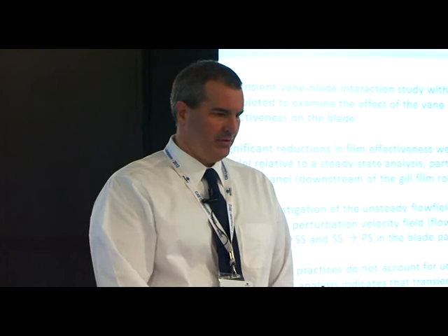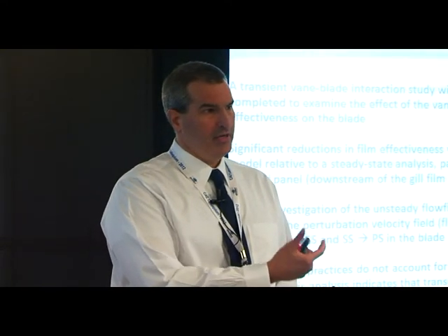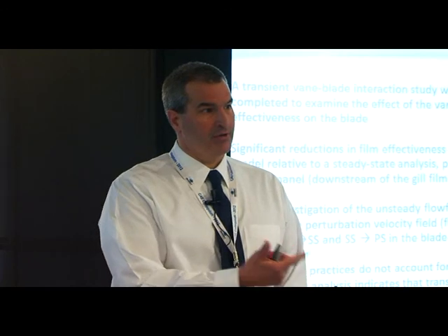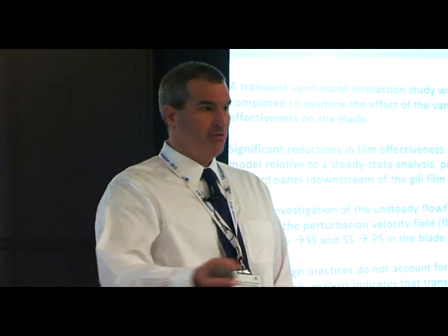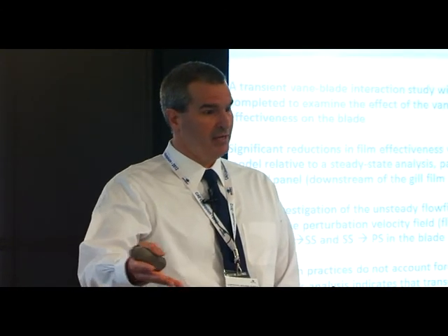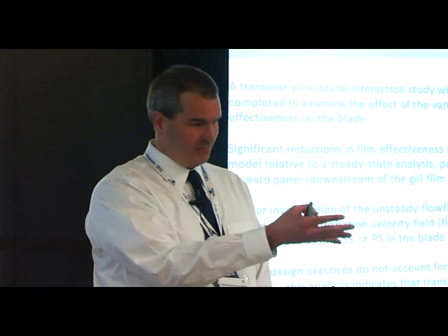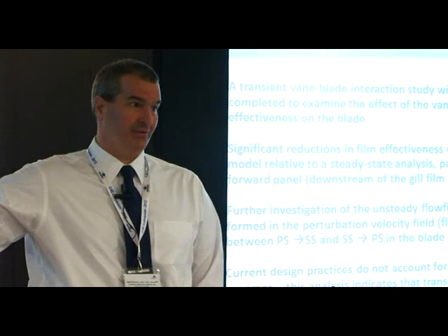I agree, but I do think the model would have to be a lot larger for an LES simulation. I would like to go back and use bricks rather than tets. And again, we were exploring. The question was why is our part burning up on the pressure side when your steady state model tells you that it's well film cooled on the pressure side? So we were just looking at this point in time.